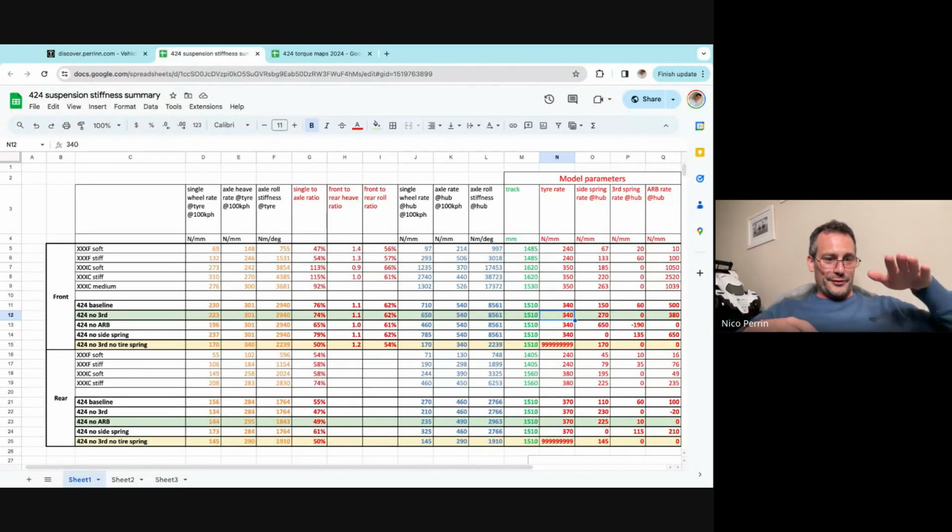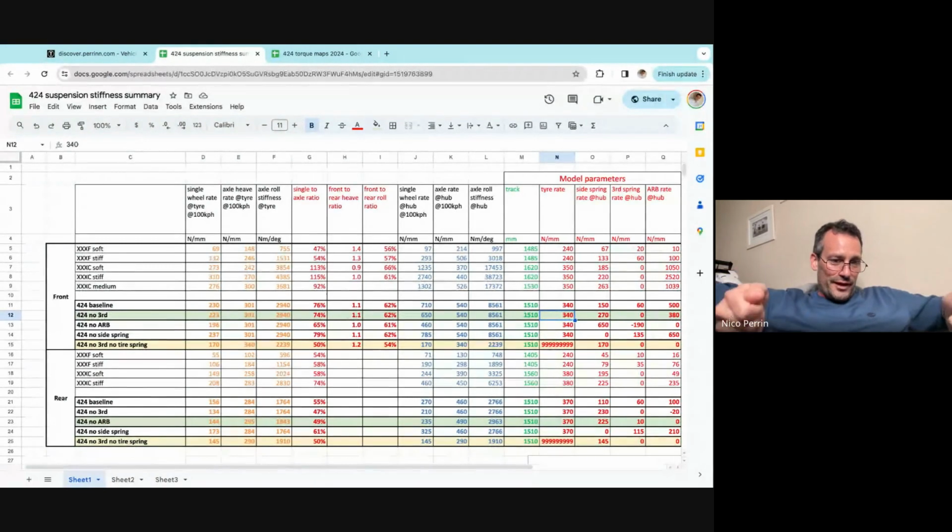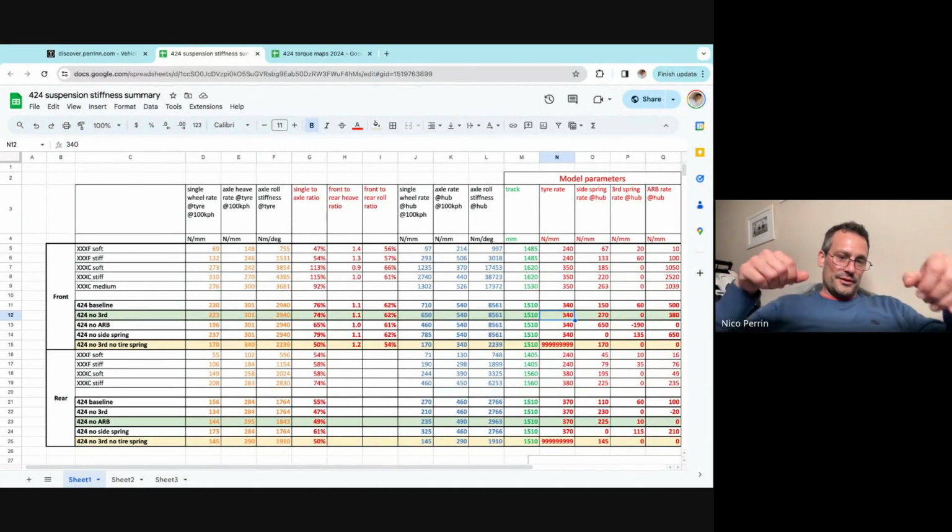Imagine you've got a table with 4 legs, the 2 front legs and the 2 back legs. And imagine the 2 back legs are on springs, and then you try and roll the table. There will hardly be any change in the vertical load taken by the back legs, because they will just deflect. But the front will be the one that will lift on one side and the other one will dig. It's the same for the car. You get that dig effect on the outside front tire and the lift on the inside front.